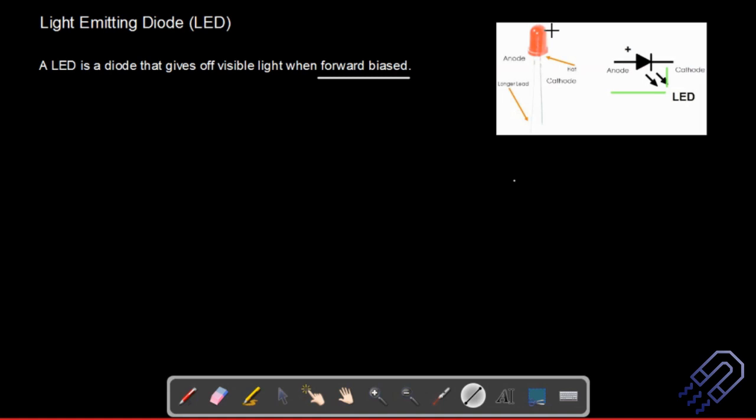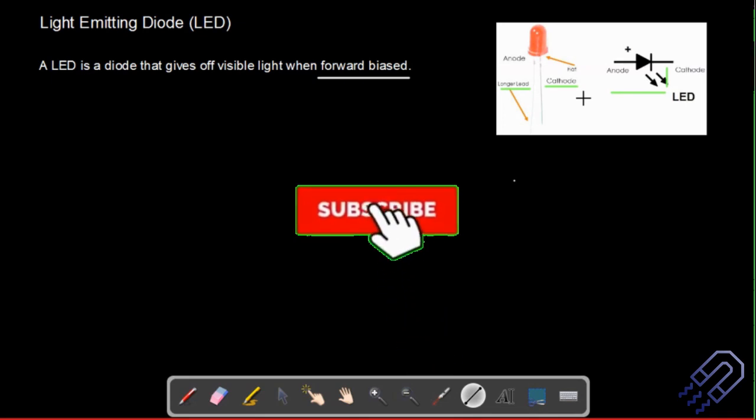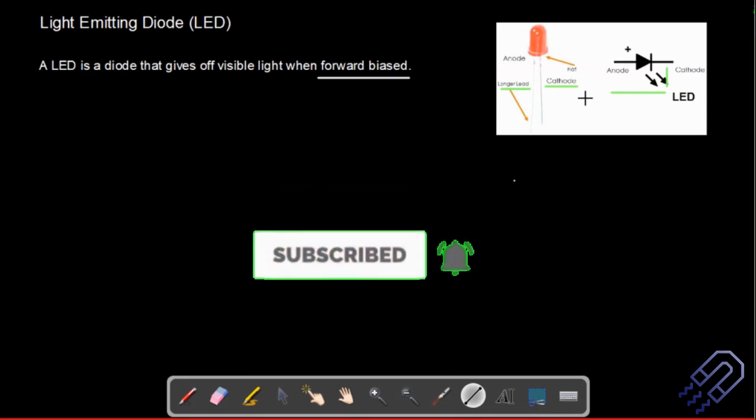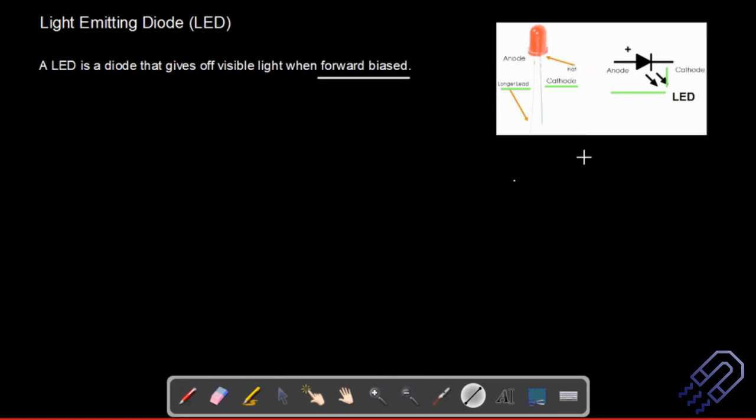And when we look into the practical device, we have the anode and the cathode. If you take up any diode, it becomes a bit difficult to know which one is the positive terminal and the negative terminal if you don't know the convention, because whenever it's a diode, one side is the anode and the other side is the cathode. The anode, or the positive side, is usually the longer lead, and whichever is the shorter lead is the cathode. An LED is available in the market for around 2-3 rupees. Different color LEDs are available, and all of them are in a similar price range.